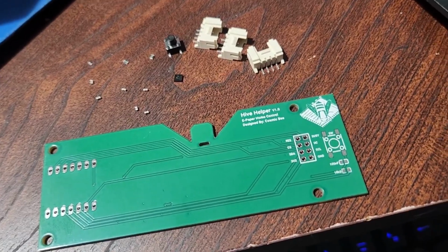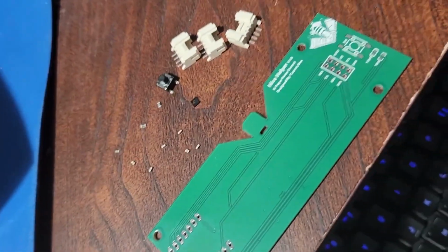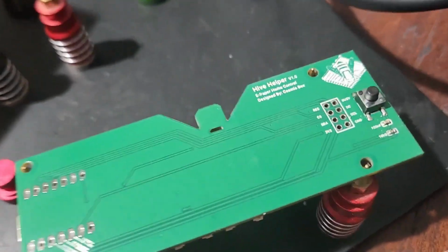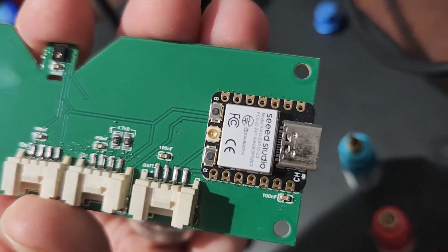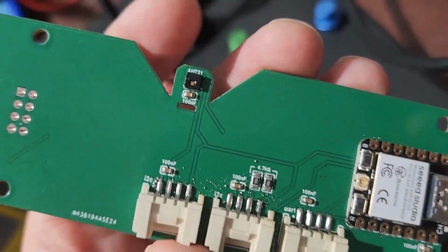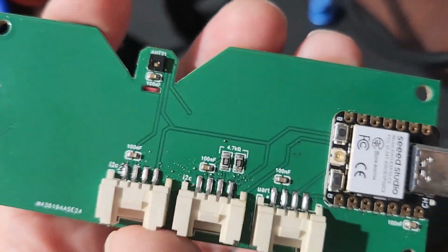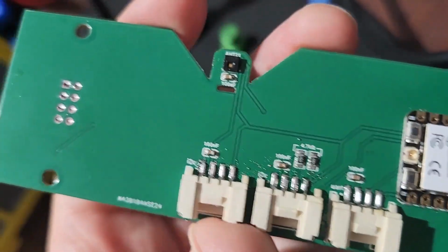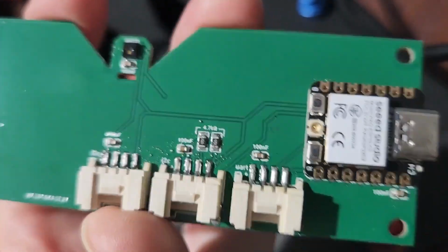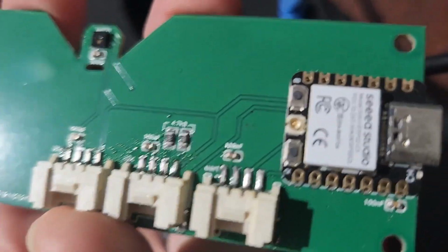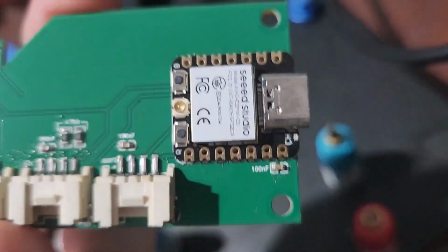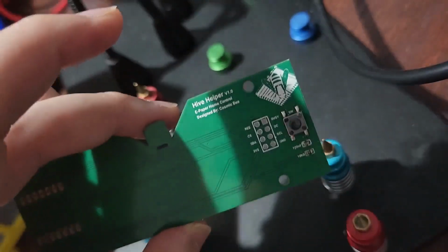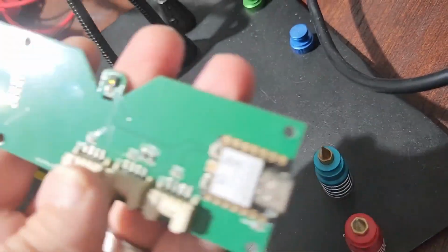I have the parts, and I'll begin soldering. The board mostly soldered except for the ePaper display. I have the ESP32C3 attached, the AHT21. I still need to clean it up. There's a lot of random solder there. The solder balls. I don't have a stencil, so I do the best I can with a syringe. But I'll be cleaning it up after. Yeah, so just the ePaper display left and then testing.